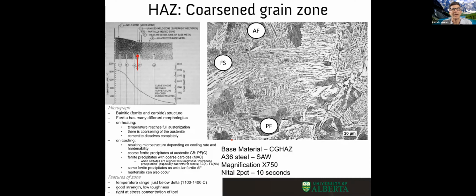And because now it became very hardenable, remember when we talked about CCTs, we said each CCT corresponds to one grain size. If we have different grain sizes, the CCT changes. As the grain size increases, the CCT moves to the right.